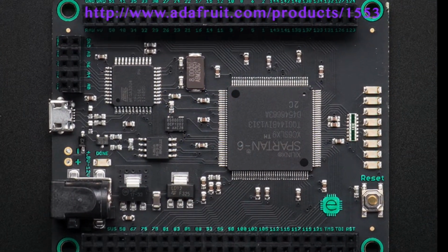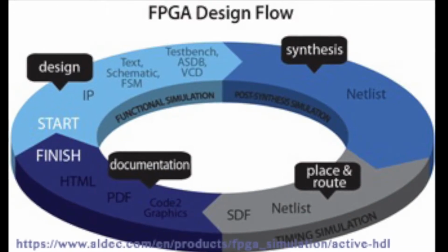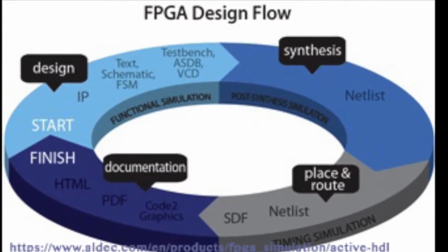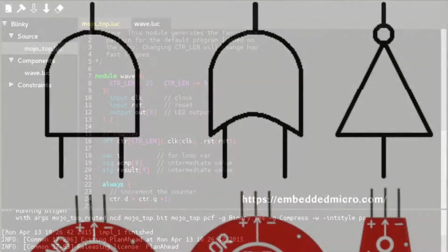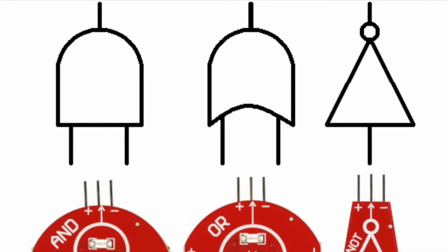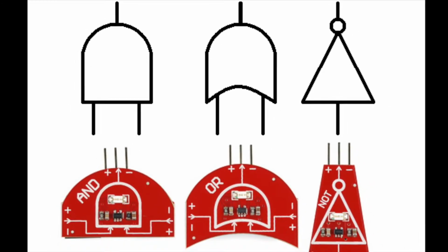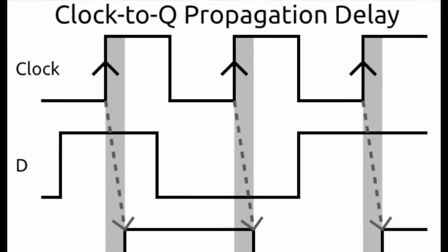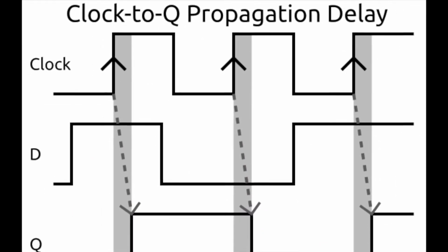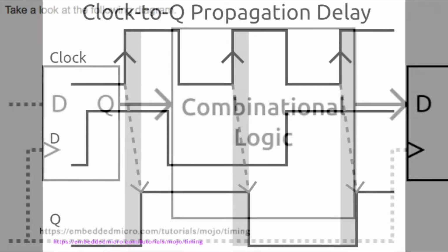An FPGA is an integrated circuit designed to be configured by the designer. The FPGA configuration is generally specified using the hardware description language, HDL. FPGAs contain an array of programmable logic blocks. These logic blocks can be configured to perform complex combinational functions. For our experiment, we will use the logic blocks as a simple 4-bit flip-flop register. These flip-flops will read through the code and determine which number will be displayed on the 7-segment display.